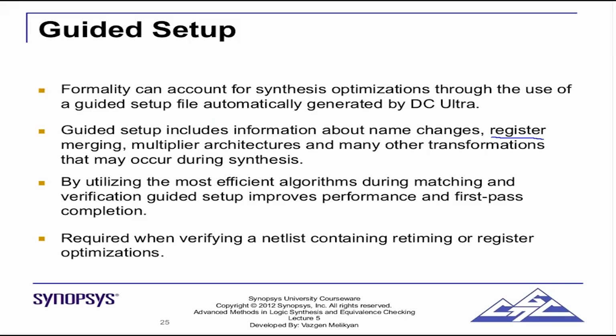Again, multiplier architecture, right? Now if you go through DesignWare documentation, you will find that adders and multipliers are of two kinds. The first is the non-pipeline, that means it is 100% combinational logic. The second ones have pipeline inside them. Now this pipeline is not fixed at a particular place. So when, let's say you are reading a pipeline multiplier in your RTL, DC will use this multiplier and then it will shift the pipeline according to the timing constraint.